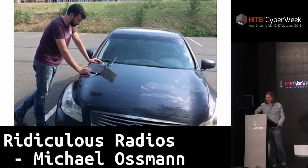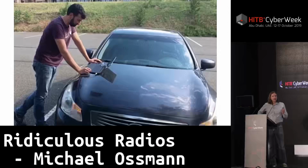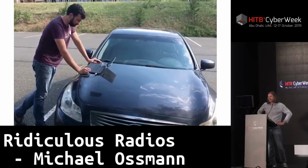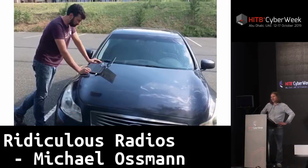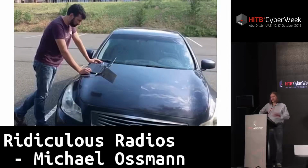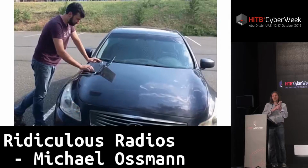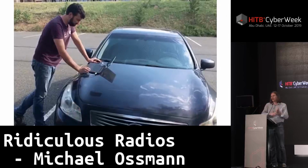Now, this happens to be a car that uses a remote keyless entry key fob that transmits frequency shift keyed data. And so we were able to successfully transmit this thing. And this demo was a little bit tricky to get working the first time because on a system like this, you have a rolling code. So the key fob generates a new code every time you press a button. And if you hold down the button, it should just keep transmitting that same code over and over again. But as soon as you release the button and then press it again, it generates a new code.